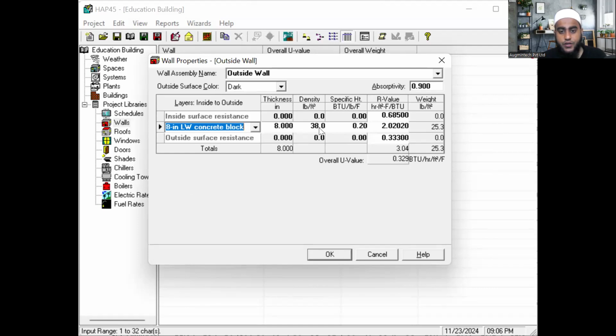As per that, they will give you the density, specific heat, even the R value. But the problem is what? Our main target is the U value. U value is also called the overall heat transfer coefficient. So U value for wall, how much? This detail you will get from the ASHRAE or ISHRAE standard.